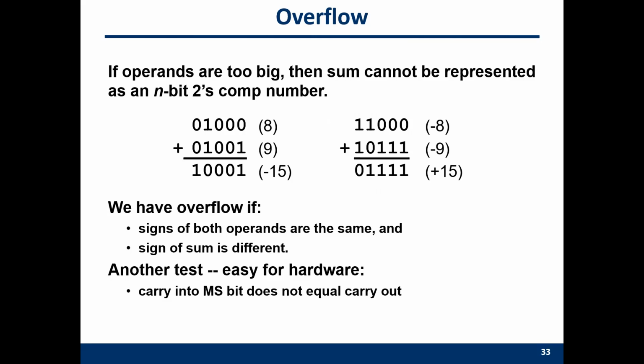So with a limited number of bits, you cannot represent too large or too small numbers. You can only represent a range of numbers. Any number out of this range will suffer from this overflow problem. How to solve this overflow problem? You need to add more bits here. You can use 6 bits to do this, or 7 bits.